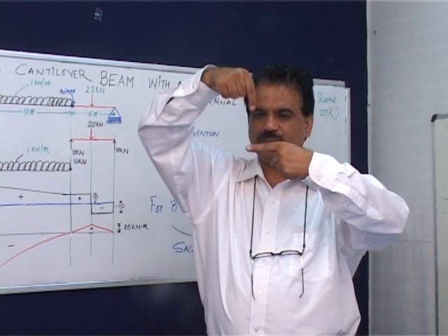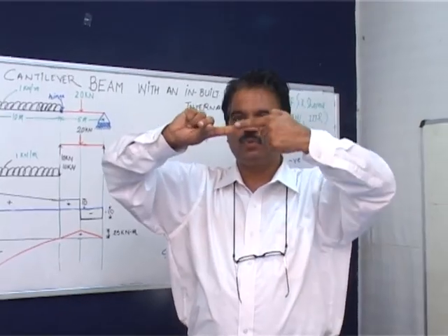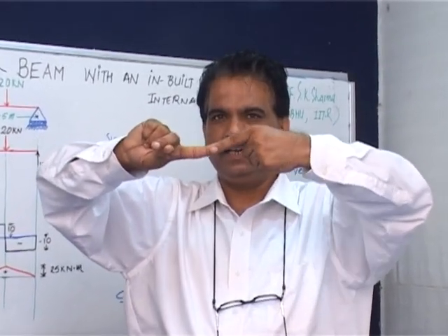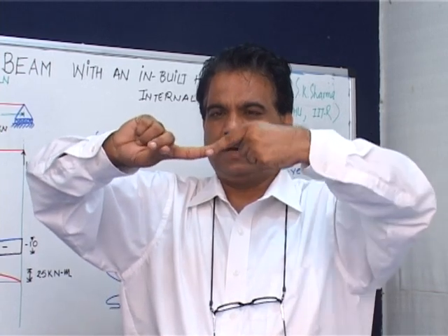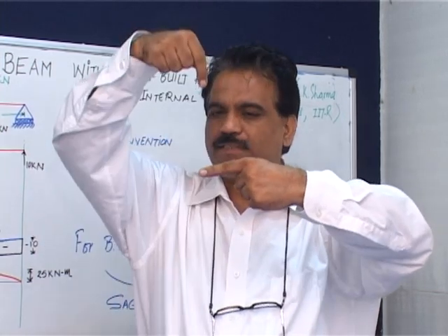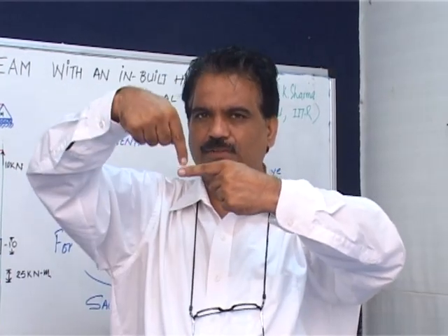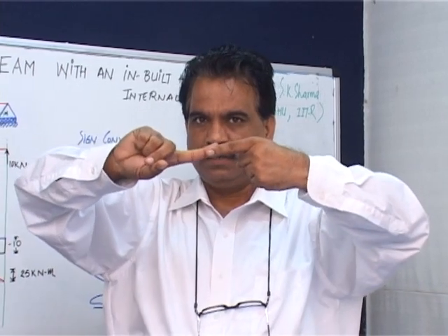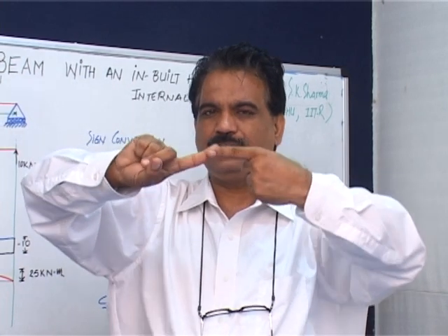What is shear force? Shear force is something like this. If this beam part, you consider shear force is something like this. The 2 beam parts joined at a hinge is just like a door where you move like that, a hinge here. And as I said, it does not resist a moment, but it resists a shear. For example, if you just want to cut it by a shear force, just want to move it down by shear force, this hinge is going to resist. So the mechanical action that this hinge is permitting is something like this.